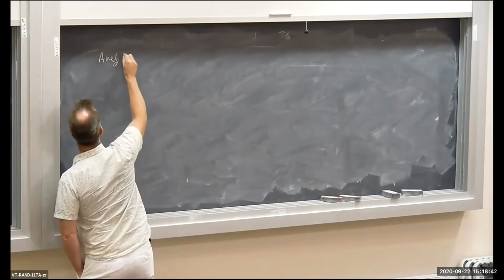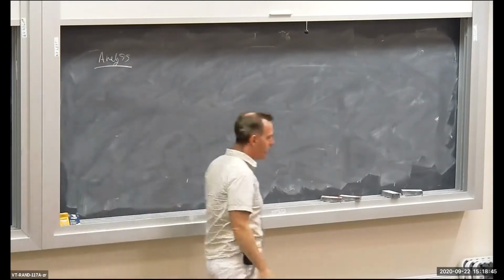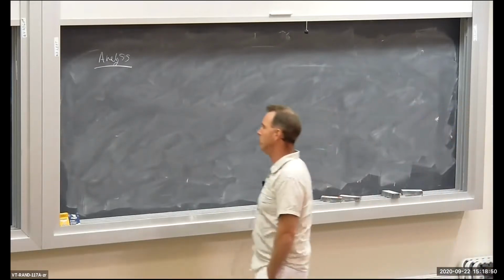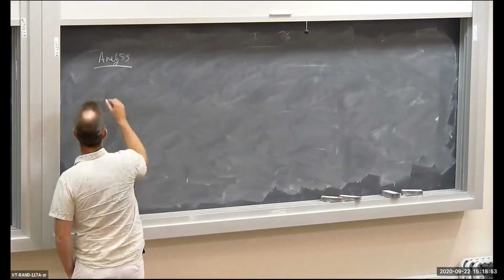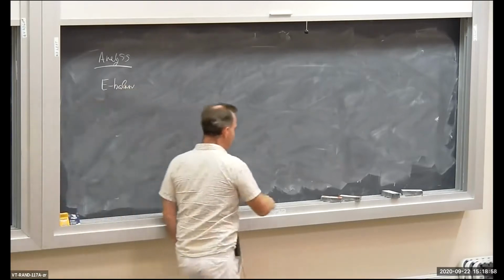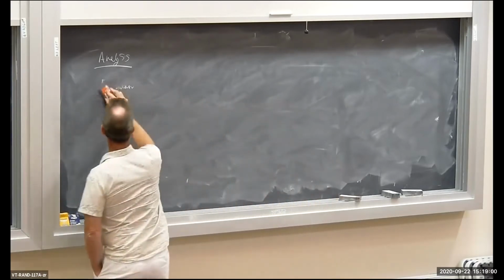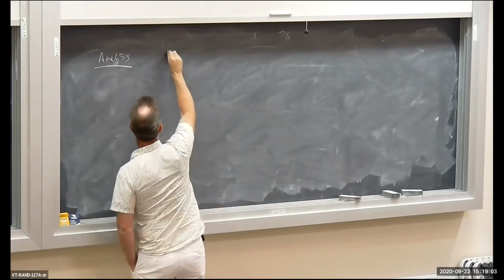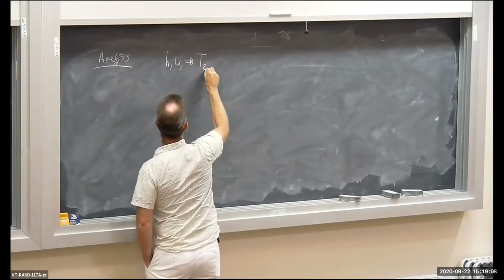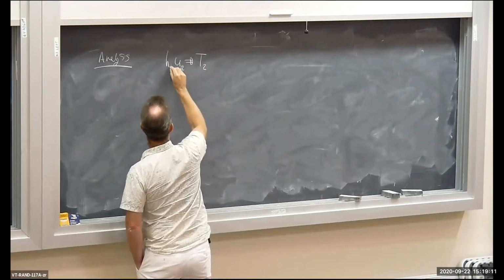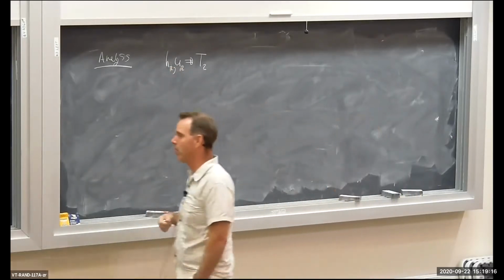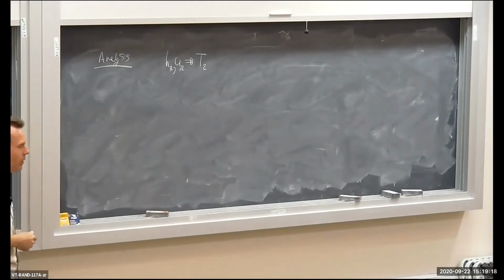So analysis. Well, clearly the equation which has enthalpies in it is the energy balance. So let's apply the energy balance to our nozzle and see what we get. So what's the motivation here? The motivation is if I know an H or a U, a specific internal energy or enthalpy, I can get a temperature at the outlet from a table. Okay, so we need to get U or H.